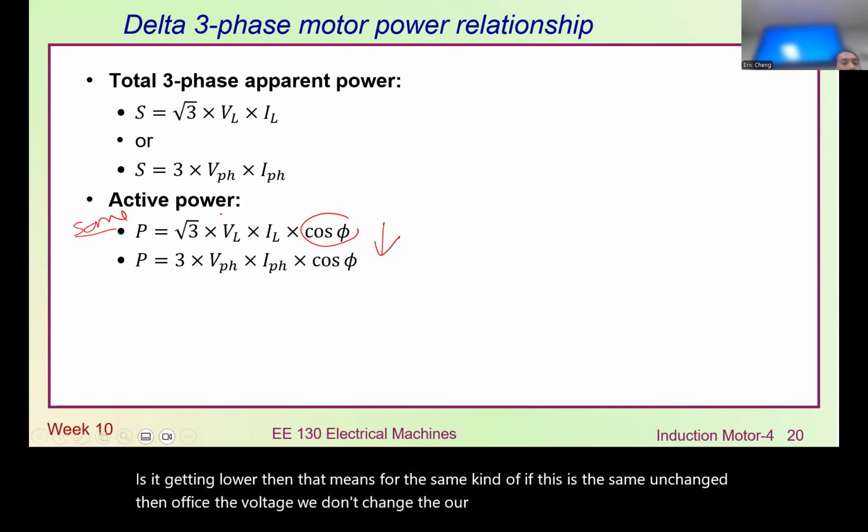So the blocked rotor test and the no-load test are the major and important tests. You must understand how to do them. In the exam, this must be there, because that's so fundamental, so basic. So we now have a voltage of 400 volt, 8 amp of line current and 1,200 watt of power, and the per-phase resistance is 1.2 because it is delta. From the delta connection, you know how to configure the phase voltage and phase current, because we need to convert them into phase voltage and current, depending on the type of motor.